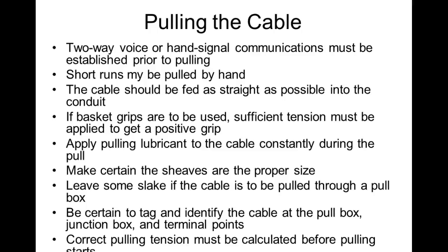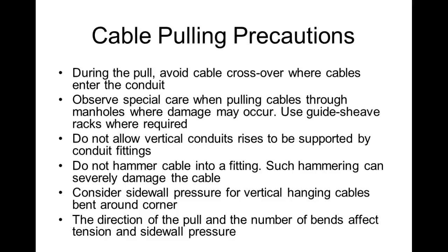We were putting a scale in down in Montgomery, and they didn't run the right size conduit to pull the cables that we needed to pull, and that was a mess. During the pull, avoid cable crossovers where cables are entering the conduit. Observe special care when pulling cables through manholes where damage may occur. Use guide sheave racks where required. Do not allow vertical conduit rise to support conduit fittings.